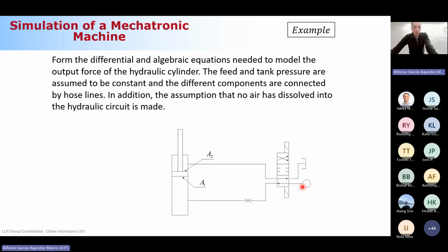So the other control volume is basically here. Well, I didn't mention it, okay, but this is the pump and this is the tank, okay? So as components, I think you are already familiar with them. You would have here a pump that is providing the pressurized volumetric flow rate. This is a directional control valve that, depending on how you move it, gives different configurations. In this particular case, you can see that the port of the pump is connecting with this port of this hose, no? So basically the volumetric flow rate is moving through this arrow, okay? So as mentioned, the answer is correct.